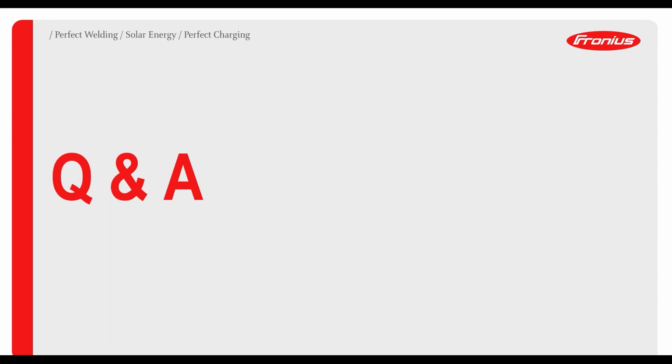That's a pretty broad one. I'm not sure with that. I mean, depending on the solution, the Intellihub meter one will be tricky, I think. The Fronius one, if it's all on the single platform, on that single login, regardless of how many data managers are on there, they'll all get the same command, so that solution would work. SwitchDin, depending how the inverters are connected on a commercial site, you can do that, but they don't have the multiple inverter functionality yet. Have to see how that works, but going forward they will have that functionality hopefully soon.